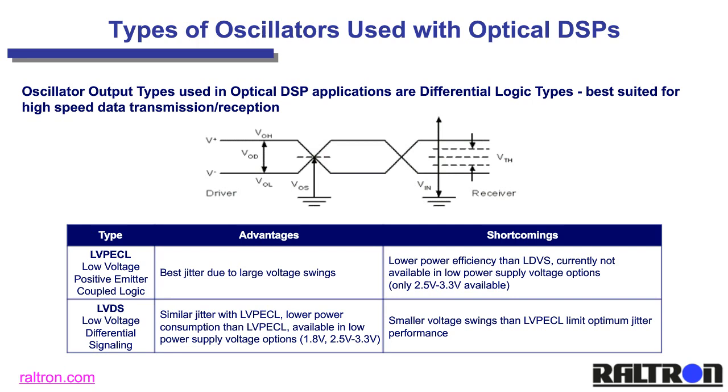But LV-PECL ICs are also improving, so it is a little bit of a race. Today we're working with the semiconductor makers, and we're trying to follow the wish list, the specifications that they are imposing. So the concentration is more on LVDS when it comes to smaller applications, and more on LV-PECL when the boards are large, because you have room to do that.